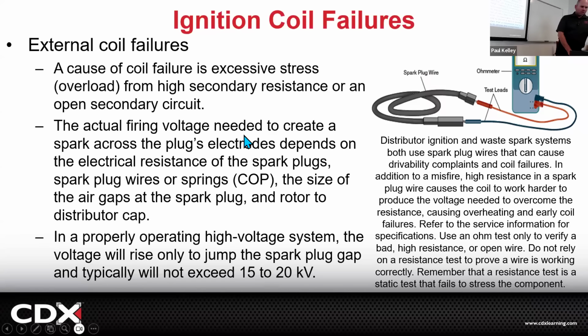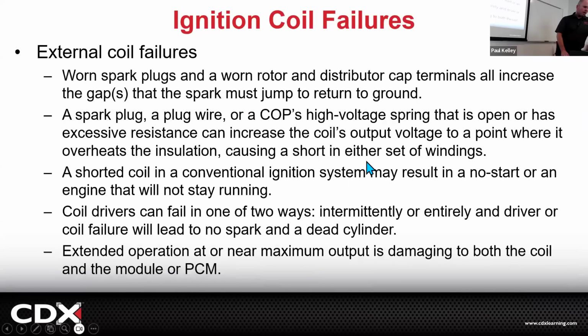Okay. So we can measure that and inspect that. But also, like it's saying, worn spark plugs will cause it to prematurely wear. On the coil on plug, when you pull those off, just remember there's a boot and a spring or sometimes like a terminal. If you pull that out and you see that it's corroded, that's going to be a failure point right there. If the spark plug has a big gap, that's going to be a failure point. So when we are doing this service, you just have to know there's a correlation. Electrical resistance, which includes a big spark plug gap, will potentially cause premature failure on the coil.